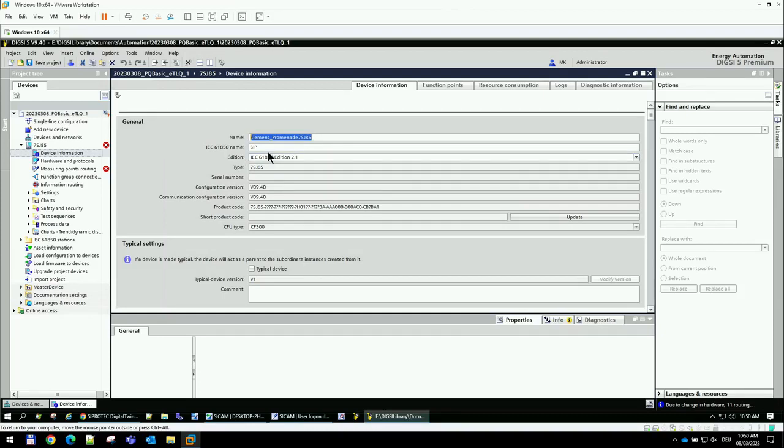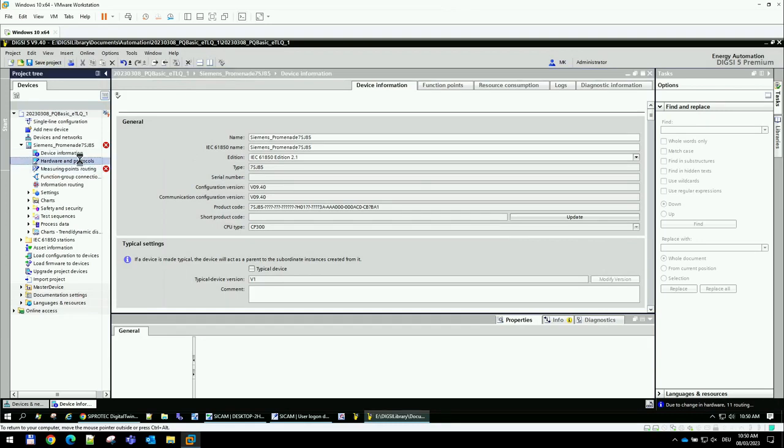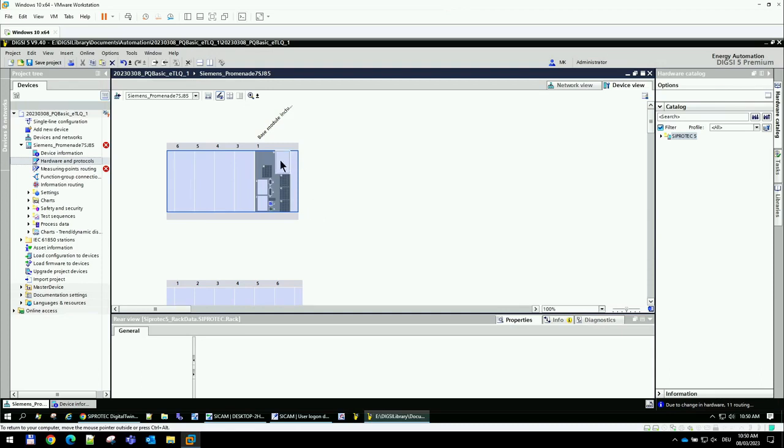No, perfect. Copy, and we will also add this name into the IEC 61850 name. All right, good. The next step will be, we have to care about how the device looks like from the hardware point of view. This means we have to add a CT and current transformer. Let us select one from the catalog.